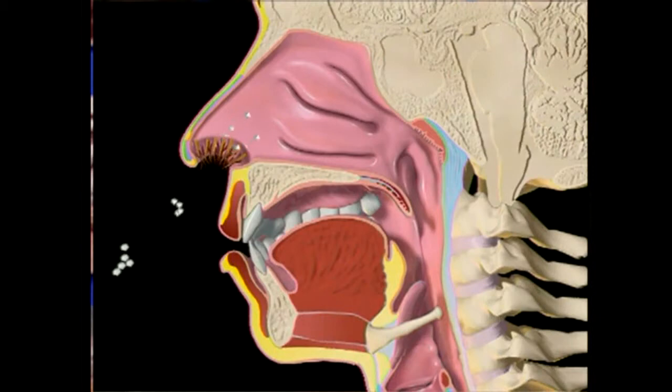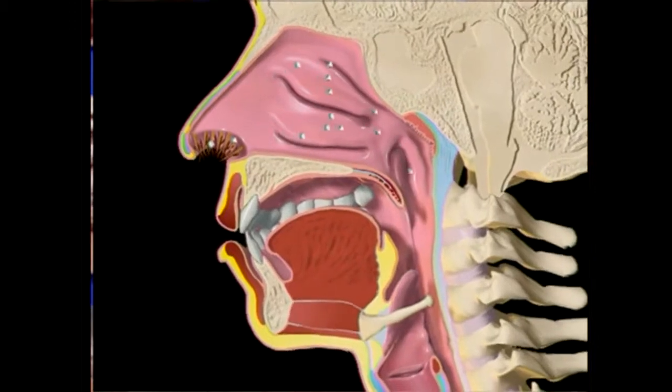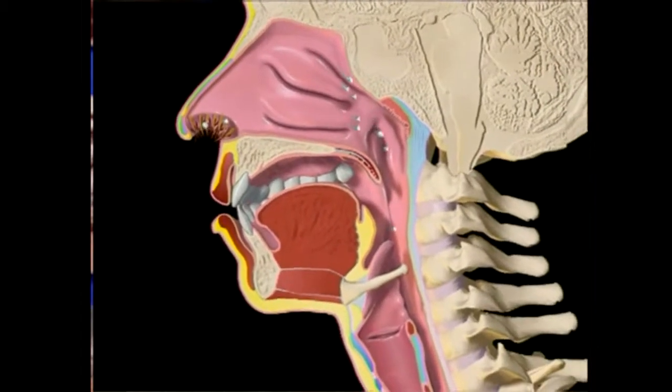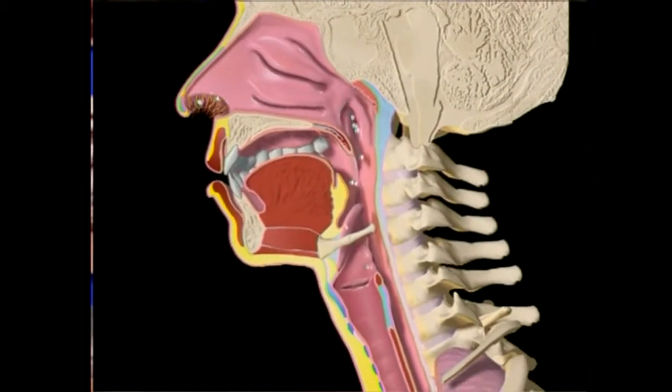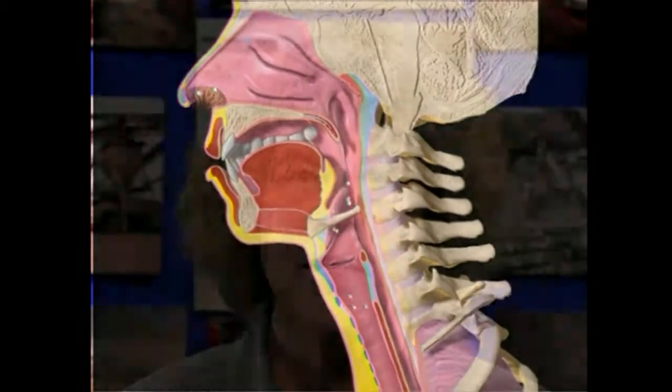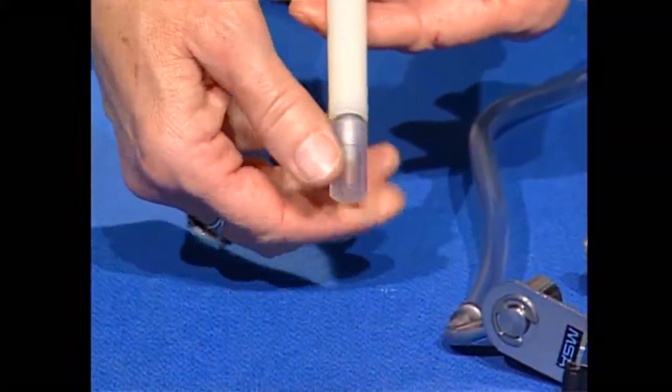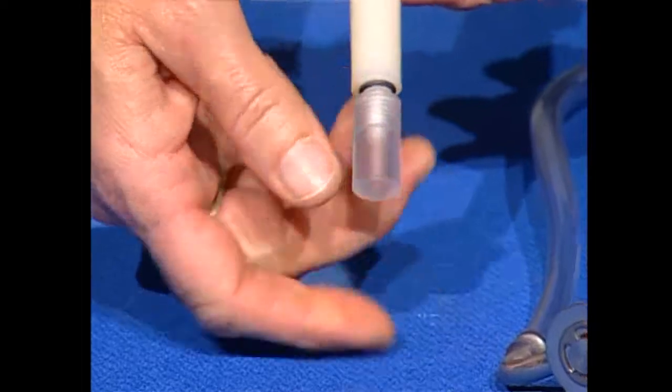It is commonly thought that the particles larger than 10 microns in diameter can be rejected from the body by one means or another, so they don't make it into the deeper part of the lungs. The cyclone sorts dust by size and collects on the filter those particles of the size range that could reach our lungs. The cassette containing the small particles on the filter will be sent to the laboratory. The large particles in the grit pot are discarded.